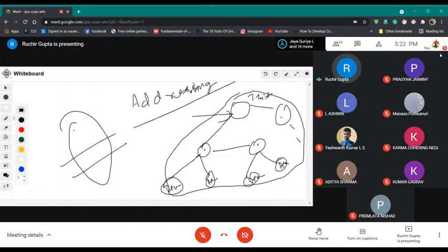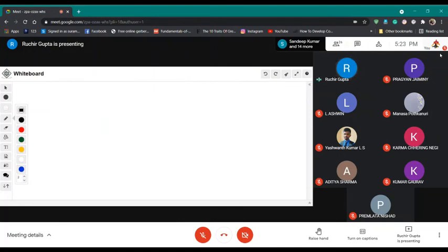The locations in the device from which this data transfer takes place are called endpoints. So where you send your status, control and data registers, these endpoints actually have a 4-bit address. If there is a 4-bit address, you can easily understand that there are 16 endpoints possible.